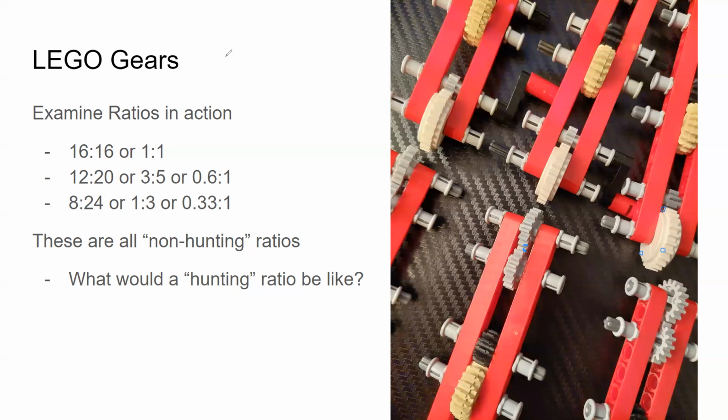Modern gears, you'll find something like a small gear with 10 teeth on it. I'm not going to draw all 10, I'll just write 10 in here, right? All right, and then a big gear that has a weird number like 41. So picture this one has 41 teeth on it, and this one has 10. So how many rotations of the 10 tooth gear does it take to equal 1 rotation of this one? Well, 10 goes into 41 4.1 times, right?